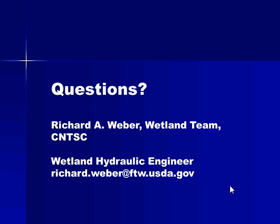I struggle with that myself, and I'm going to answer that question in two separate components. If we actually know the groundwater is physically discharging under hydraulic head, we've got a qualitative assessment of the hydrology of the wetland. We don't have any quantitative assessment. Coming up with the actual volume of inflow is extremely difficult and requires probably more investigation than we can afford to do. I'm sorry that's the answer, but that is.